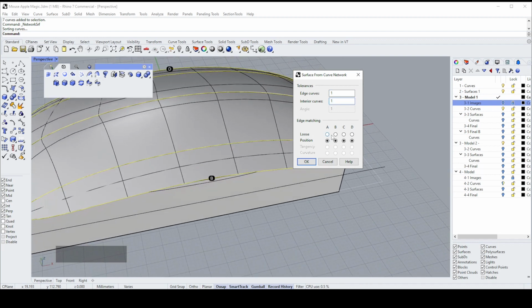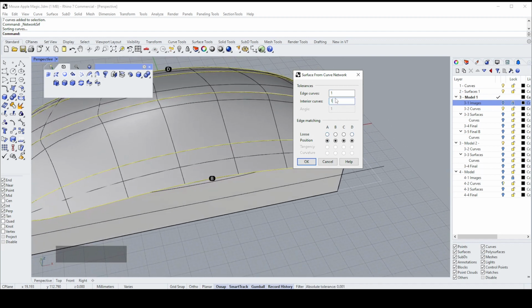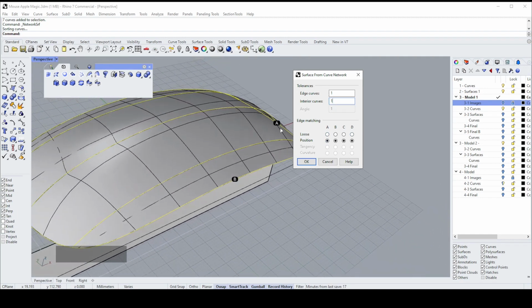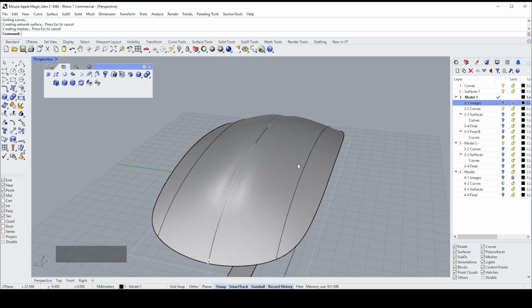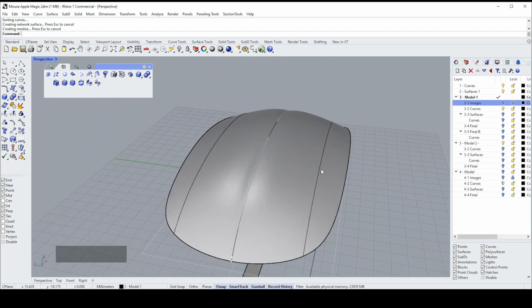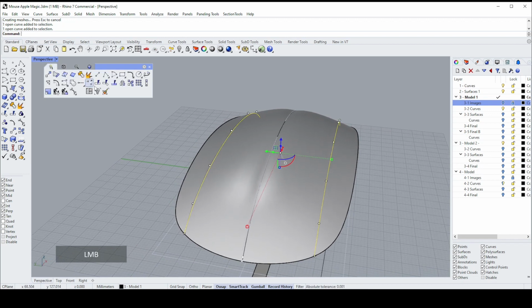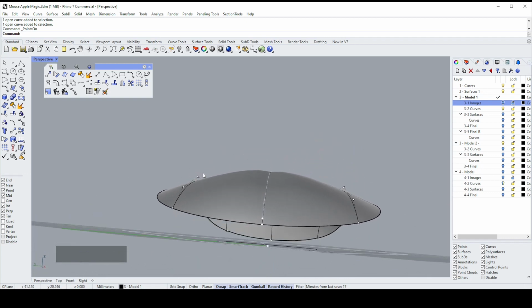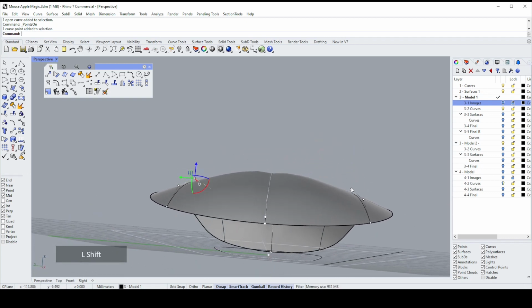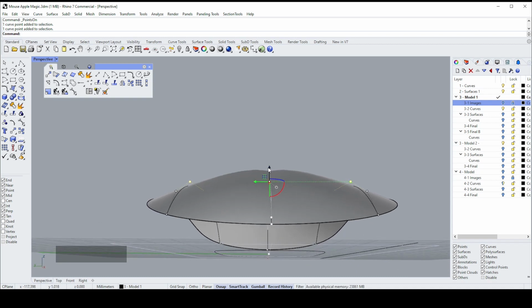We don't want to loose it. Loose will do the same thing. It'll actually get the surface to extend beyond the curve. So say okay. Right, here's where the magic bit happens. Well, it's all magic, but I'm going to select those 2 curves, and I'm going to just show their control points. And now what I can do is select in pairs as always these, and I can adjust them up and down and left to right to get the surface to behave as I want it to.